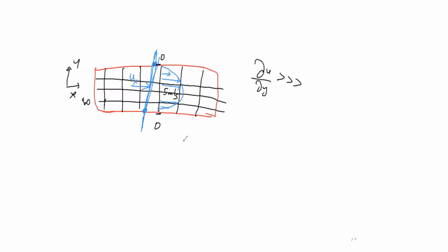So what I'm doing is, I have created a probe, and then what I'm plotting in ParaView is, on the x-axis I have the y distance, meaning from here to here the distance. So this is 0 from the distance point of view, and this is, let's say, 5 meters, which is very large, but it's okay. From 0 to 5 meters, I want to see how velocity is changing. On the y-axis I have the x component of velocity.